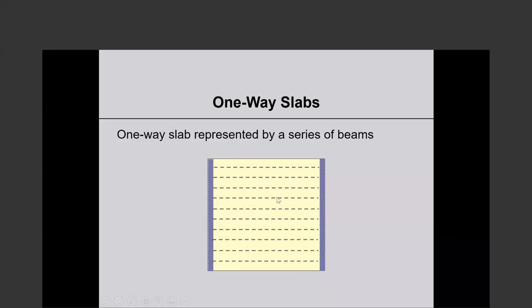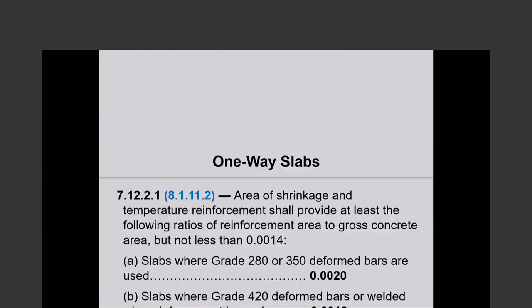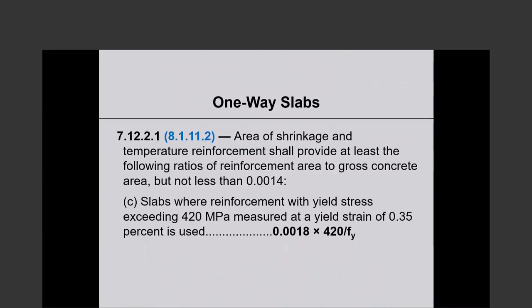And whatever reinforcement you calculate for that 1 meter will be provided. So we will calculate the spacing and we will provide that reinforcement spacing throughout the slab. So that's what is kind of illustrated here.